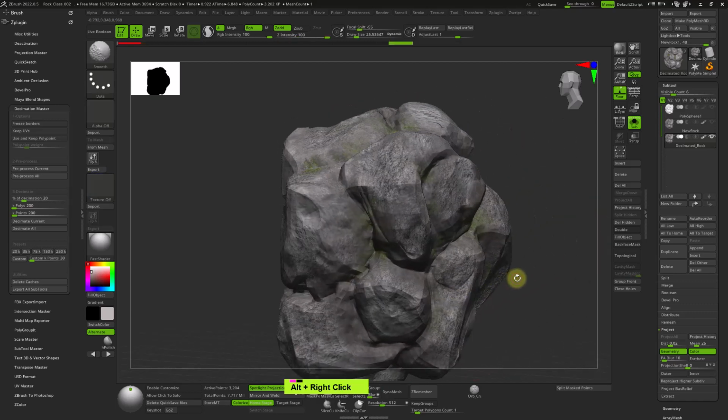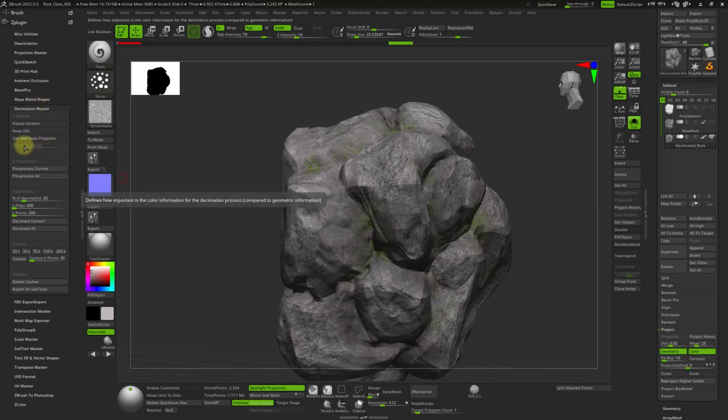This is good, but it lacks details. And when you are exporting to your software, Maya, Blender, whatever, and yes, you can get back the details through displacement. Yes, of course, but that costs you time and money. And if you have an AR application or you want to use it in Unity or Unreal, then you don't have that luxury to always subdivide things. And so you want to use a solid mesh that's not changing up. But through decimation, you can create level of detail LOD models.